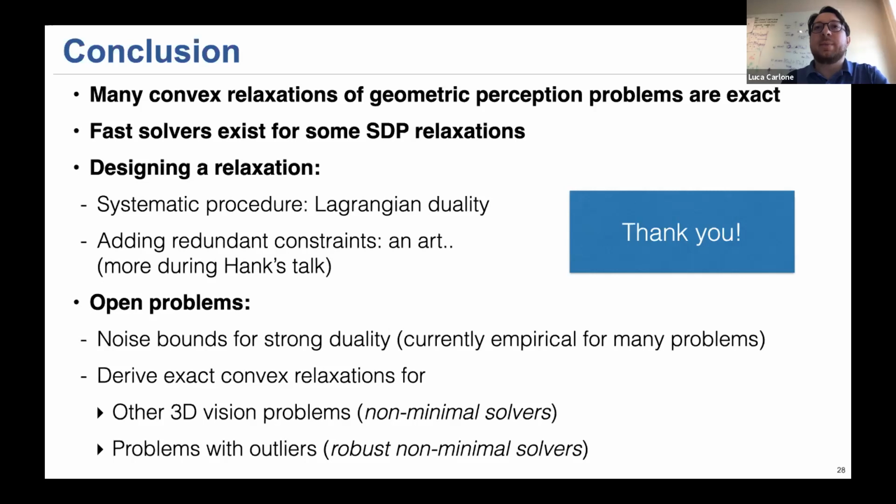So there is a question about the determinant constraint that I dropped from the derivation. I will try to address a bunch of questions at the same time on this determinant constraint. The basic idea is that if you drop the determinant constraint, you can get both rotations and reflections, right? Reflections are typically not a physical motion of the robot, so you don't want that, you want proper rotations. So what is possible to demonstrate, and I think David has a proof for that in the SE-Sync paper, is that